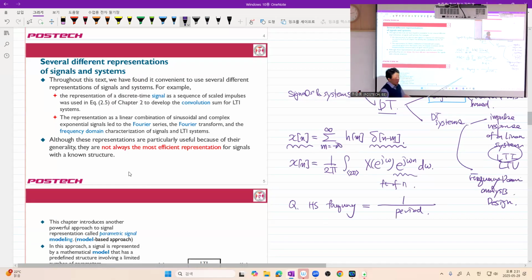However, in our DSP, when we say frequency, what does it mean? What is the value of omega in our Fourier basis? Okay? So in the Fourier basis, e to the positive j omega 0 n is different from, in general, e to the negative j omega 0 n. They are, in general, different signals.